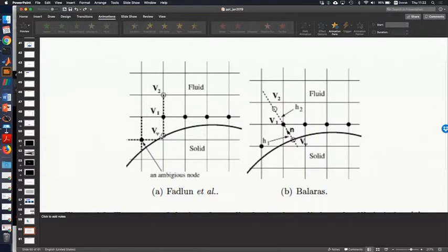You can look at the cells that are present in the grid, and you can take the surface cell, or you can say, okay, I want to look along the normal of the surface. And then there's this new cell where I have to figure out what the velocity is by doing interpolation from its surroundings. So there are several ways. And these approaches have issues. If you have a sharp corner, I might not have suitable cells surrounding me, so I don't know how to do the interpolation. And there are ad hoc fixes.